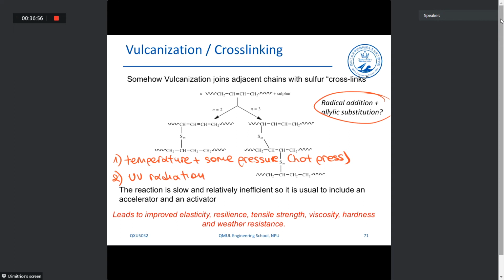You remember that we were talking about how a rubber band can suffer if it's left for too long under heat, because the combination of both increased temperature and UV light can lead to a very high degree of cross-linking points. And as we said, in order for an elastomer to show elastomeric properties, we need the amount of crosslinks to be low. Okay, if it's high, then the rubber band snaps very fast.